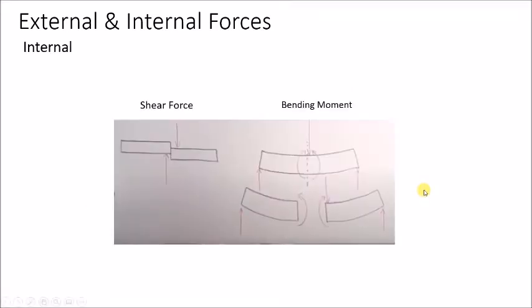So another thing that tends to happen when we apply a force to a beam is, if we look here at this downward force, the beam will actually sag or bend, and the internal forces that are reacting to the external loads and forces that we've discussed are called shear force and bending moments. These are two of the internal forces that the beam will undergo. We're going to take a look at them in more detail now.